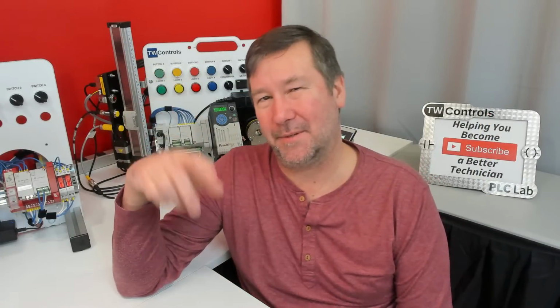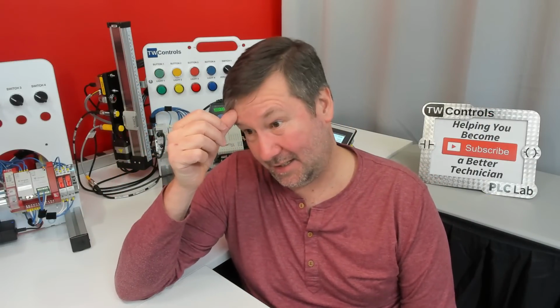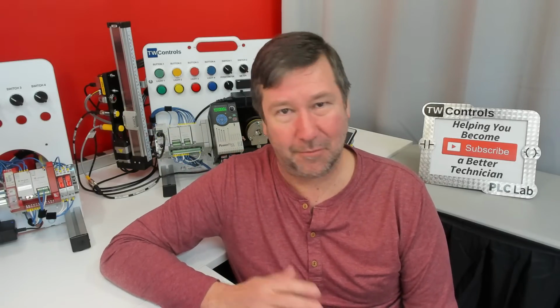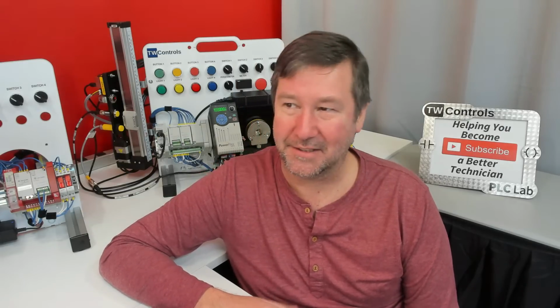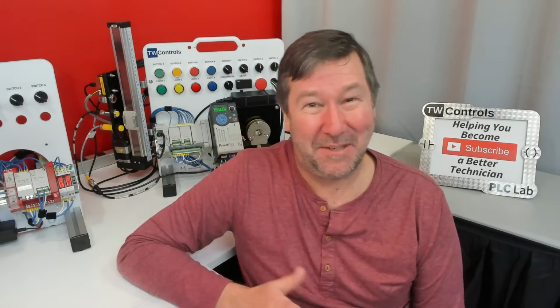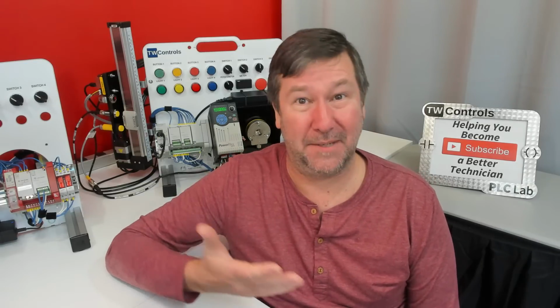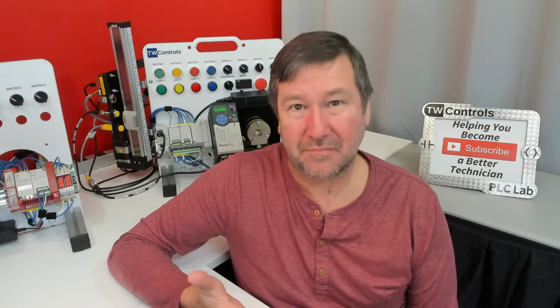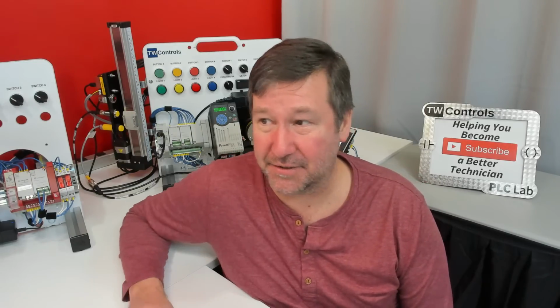one, the simulators do not work exactly the same as a PLC. And I've run into that. People will be like, hey, I'm trying to test this code and it didn't work the same when I got out of the plant. I'm like, what are you testing your code on? They're like, a simulator. I'm like, have you thought about putting it into a PLC? But you're getting ready to probably spend a large investment on a plant upgrade or doing something. Go ahead and get you a PLC to actually do some testing with.